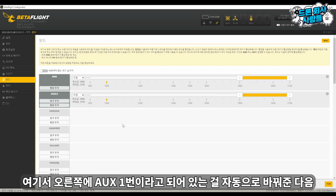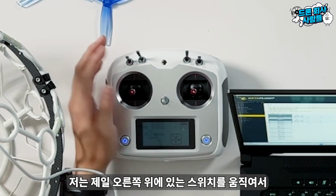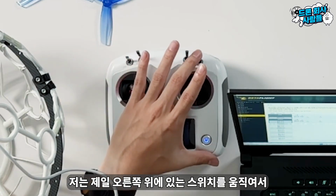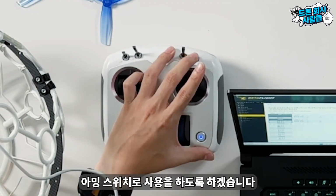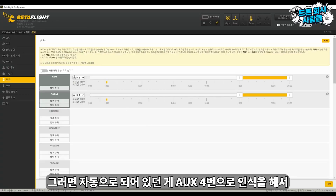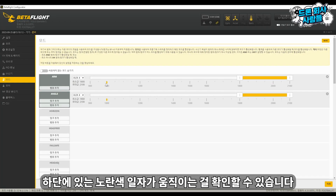After automatically changing it, you can move the switch you want to use as the arming key. I will now move the switch at the top right and use it as the arming switch. Then what was set to automatic will be recognized as AUX4, and you can see the yellow line at the bottom move up and down as the switch is toggled.